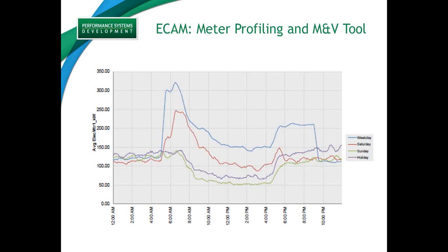help you, if you have access to that kind of interval data for your building, see these trends and understand, does that line up with the operation, with the schedule of the building? Are they coming in at 5 o'clock in the morning or 6 o'clock or not until 8? Are there opportunities for turning on equipment later?